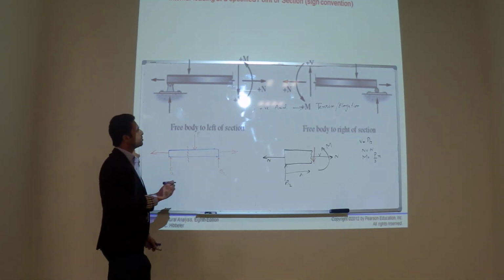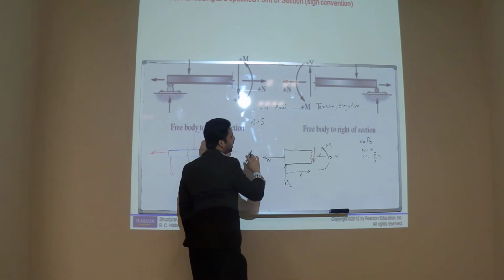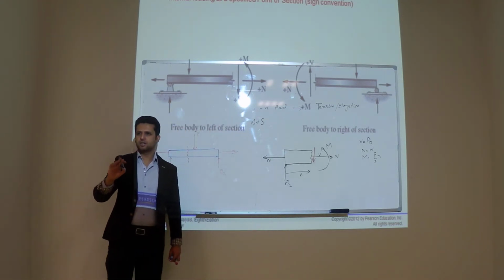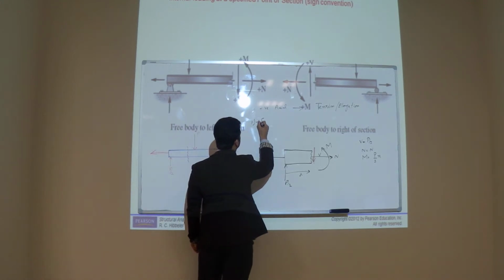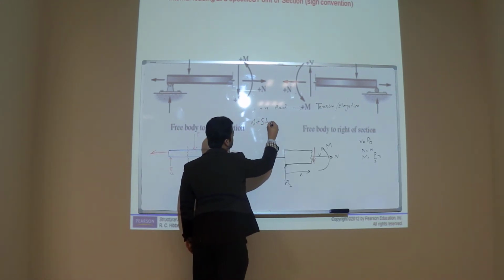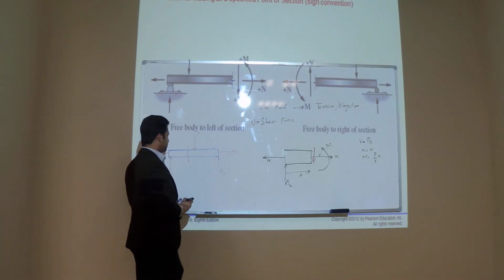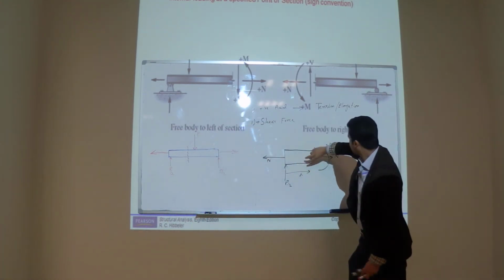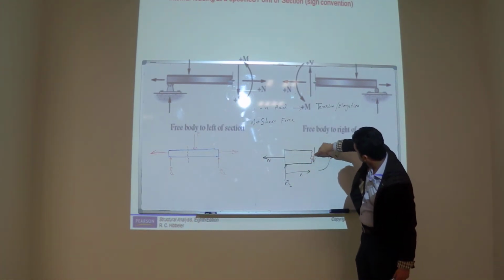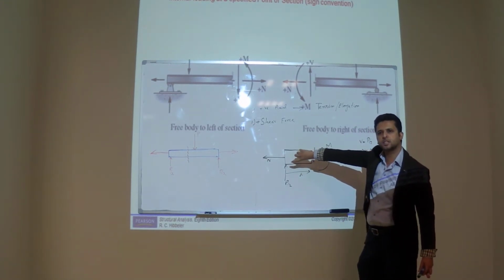Number 2, shear force. I'm just telling you the positive. The negative will be the opposite. Positive shear. If you see, this shear force is trying to rotate this with the help of this reaction in the clockwise direction. Can you see?